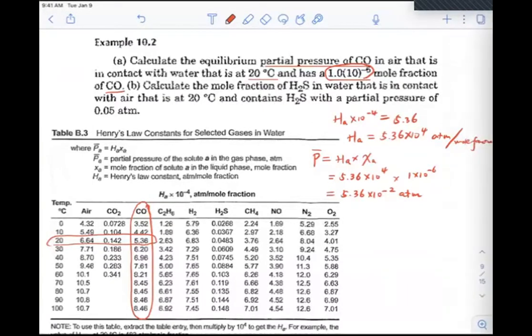With this Henry's law, you can see that if you want to absorb any VOCs or any gas, there's always going to be a constant that determines the amount that you can absorb. It depends on the vapor pressure of the VOC species in the gas phase, and if you have the liquid, then you can determine the mole fraction, or how much of the VOC you can absorb.